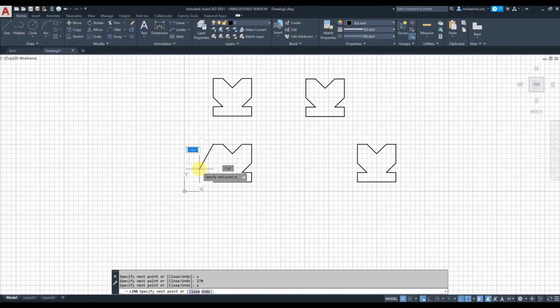So in this case, let's go ahead and use Cartesian coordinates. So 0 along x, -2 along y-axis, right? So that worked well for us. Let's go ahead and do Cartesian here. 1 along x-axis, -1 along y-axis. So in this case we're gonna do -1 along x-axis, 0 along y-axis, and you can click the first point and escape.